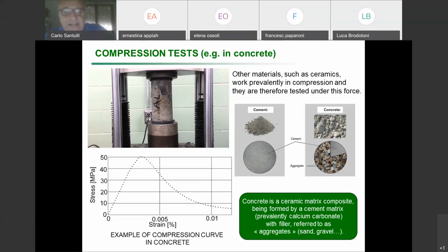On concrete, there are more difficulties to measure the Young's modulus, because you usually start showing some deviation from linearity. It is less ideal than steel. It shows some deviation from linearity, so you probably would need to stop somewhere linear to understand the intercept of your curve, which is the line you need to consider.